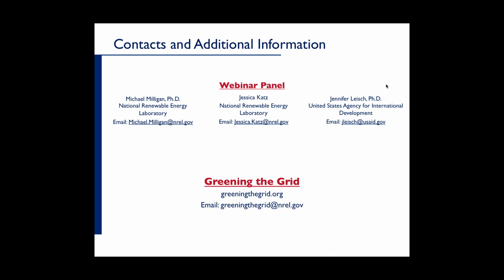And I think the other interesting source of flexibility is coming out of two different sources. Aeroderivative turbines, which are basically jet engines turned into generators. They can ramp very quickly, they can start very quickly, they have minimal heat rate degradation at startup and over the ramping cycle. They're pretty efficient. And so that's one source of flexibility.